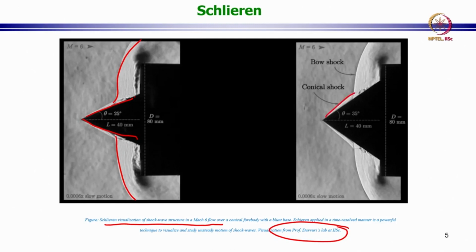So, here you can see this shock formation, right. There is a difference in the grayscale images in this background over here and, let us say, the grayscale here. So, the shock wave formation is very clearly seen. What you do not get is data regarding the velocity field. So, these are not quantitative in the same way that particle image velocimetry is, but you can use data from this to visualize how the shock wave changes, etc.